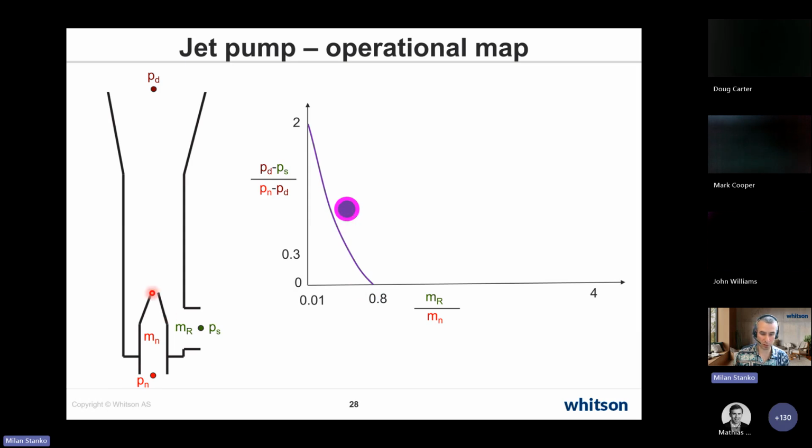So this is the annular section. The nozzle, the area here of this nozzle occupies a significant part of the throat. Okay, it's not like in this picture, but actually occupies a lot. If that's the case, your pump will behave in this way. You can reach very high delta Ps, and then you have to inject significant amounts of the power fluid. Okay, you see here that one will be the same amounts, in mass, talking about mass, but here we go to 0.05, so that means that you're injecting quite a lot compared to the reservoir fluids.